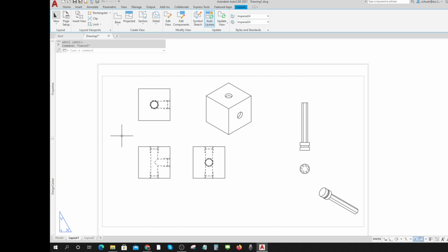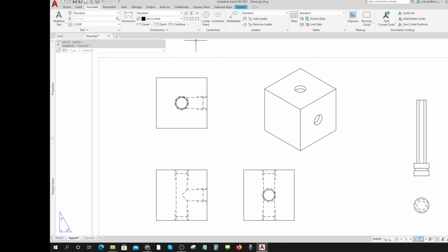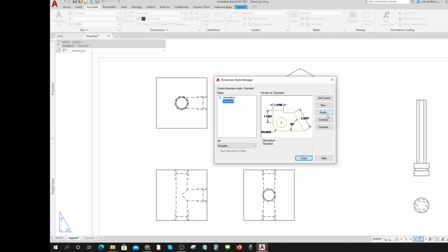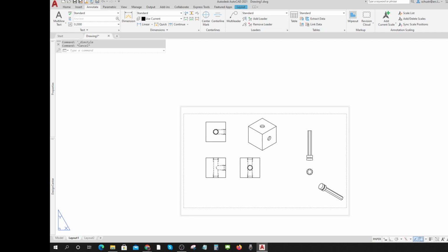Now I'm going to do the next question in the way that works for both AutoCAD and for Inventor. We know that in AutoCAD, I can make things called Dimstyles. I can go here and I can set up many different Dimstyles with my Dimstyle manager. And I can even do that in Inventor, but in Inventor, they sort of do it one by one. So I'm going to show you how to do that one by one here.